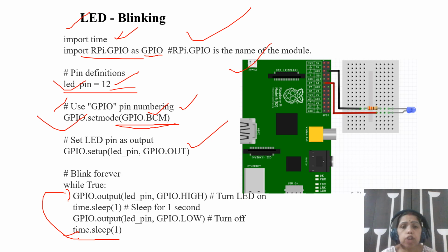So I think it is clear for all of you. If you need to use the GPIO pin, you have to write the code accordingly. If you have mentioned the pin, then you have to configure the GPIO pin configuration, set mode. Two libraries are there: import time and import RPi.GPIO. Next class I will discuss the LED, same code, same aim, but here the LED will turn on and off.